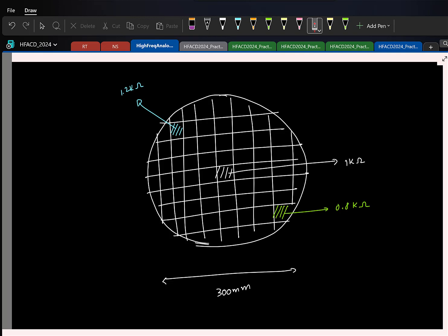In that blue chip also, you designed for 1 kilo ohm. Basically, all of this will be the same design. In the wafer, you will have the same design put in all the chips. So nominally you expect that each of these should have a mean value of 1 kilo ohm, but once again, due to the variations in the process, you will have differences in the mean value also. And this is typically called the process variation.